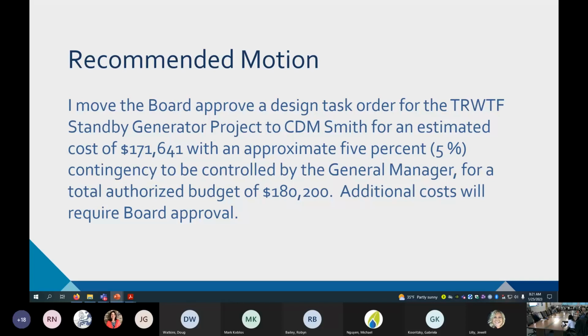So in terms of communication with Novik, it's going to be more about the discussion of whether there are adequate safeties in place to avoid feeding power back to them, somehow the energy going back to them as opposed to going into our facility, and the paralleling of the power, making sure that they're okay with that. And so that's probably the extent of coordination with Novik.